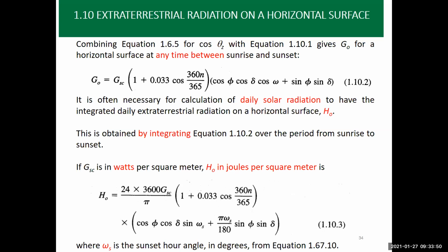So that was basically dependent on how much water they are using. So for a hotel, what is the average occupation rate? And accordingly, how much water is going to be consumed roughly by a person, how much water they need for the laundry, for cleaning, and so on. And we estimate in general how much is the total consumption of water. Out of this water in winter seasons, how much do they need water heated? Definitely, winter season is going to be higher than the summer season, but there are some applications that will not be affected by the season where you need hot water.